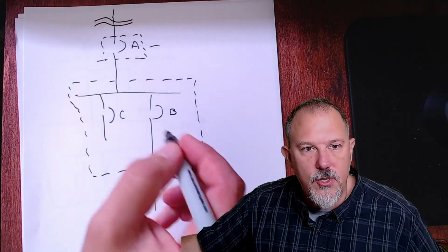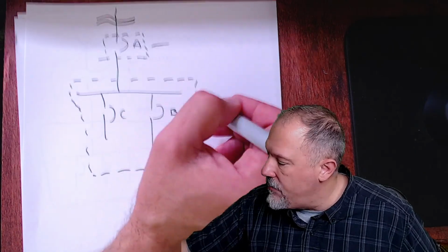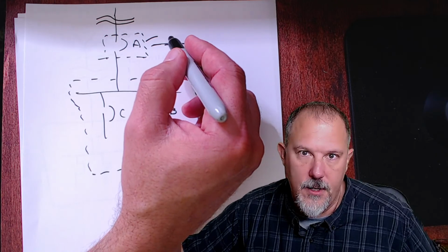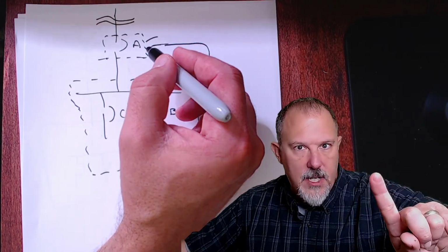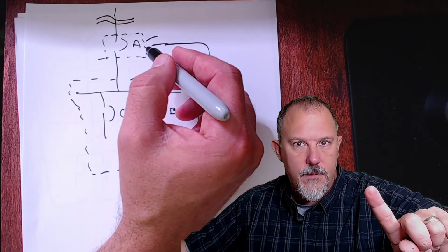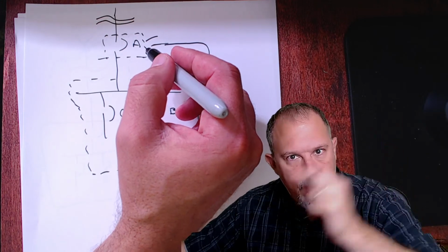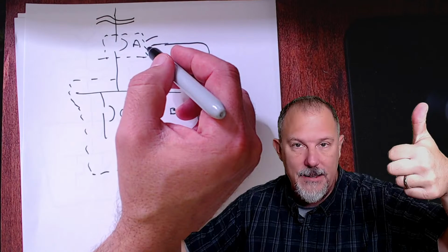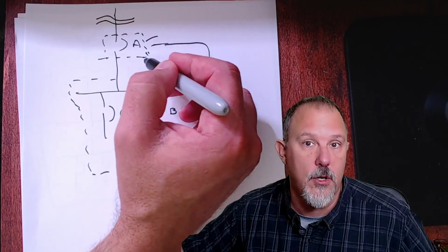That now I can reduce the energy. What did I do? I moved the energy up here. The likelihood of having to get into an enclosure with one overcurrent protective device, my service overcurrent device, is low. The incident energy is very high. If I have to get into this piece of equipment, I call the utility and tell them to turn it off.